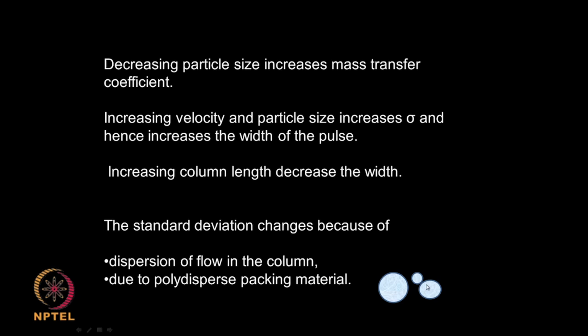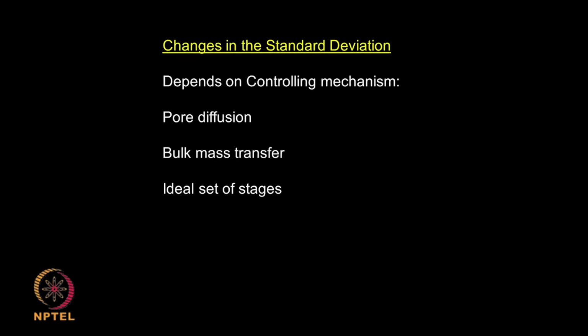Although I say the particle size is, say, d, you will never have a very uniform particle size. The particle size may have a small distribution. Because of that polydispersed nature, the standard deviation could also be changing. So, standard deviation is never a constant, but it could be a small distribution depending upon the polydispersed nature of the packing material. So, changes in standard deviation depend on the type of mechanism.